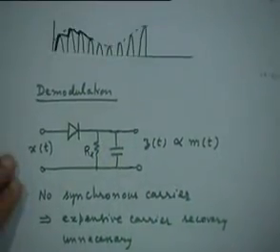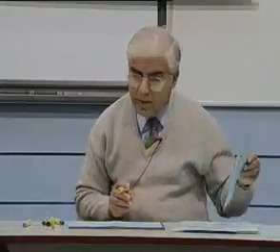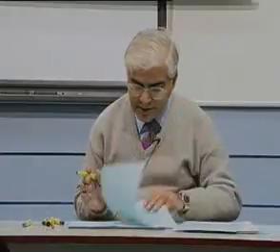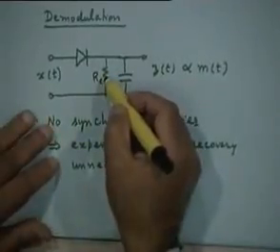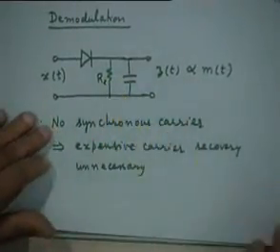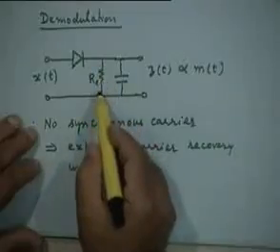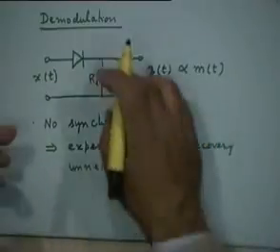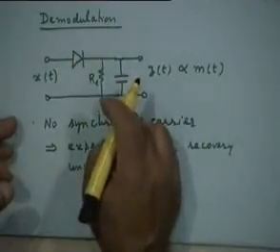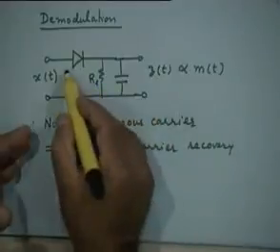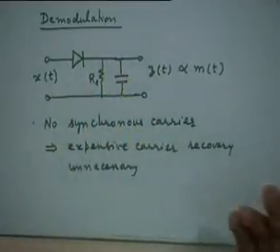Is that clear? Okay. So what is the RL? RL is this load resistance that I've talked about. Then why are we saying that RL is far greater than RS plus RF? I just explained, because if you assume that, then this would not come into the picture of the charging time constant. This will be so high that the charging current will hardly flow through this resistance. Most of the current will be used to charge up the capacitor, right? And we don't have to worry about the value of R sub L in calculating the charging time constant.